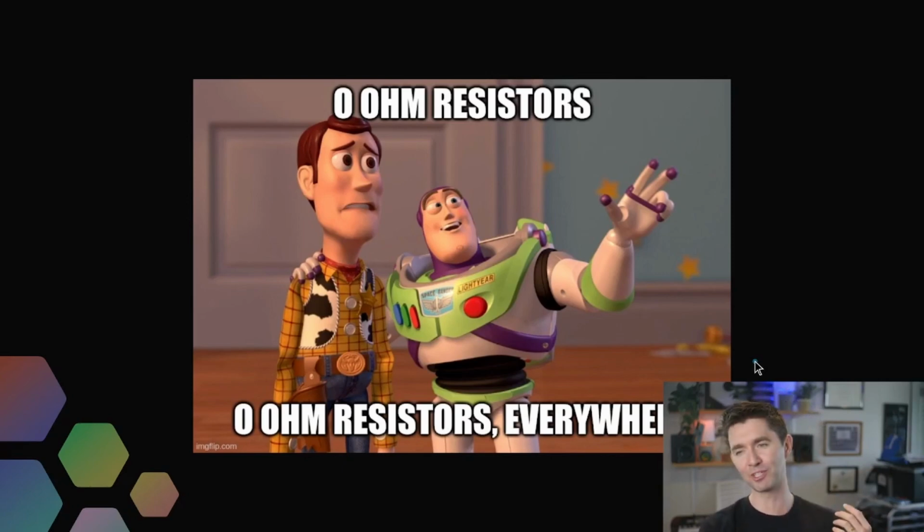And if you are a firmware engineer and you're looking at your hardware engineer's board and you're like, wait, where are the 0 ohm resistors? Ask about that. Suggest it. I think it is an important thing to have on your first prototype.